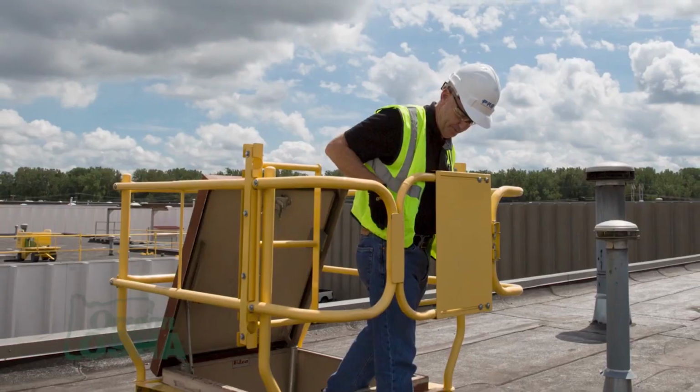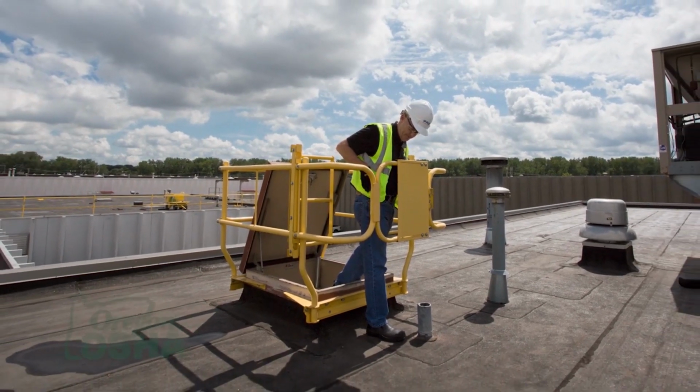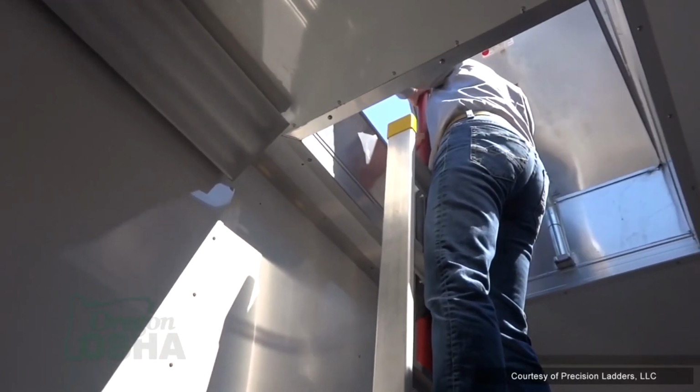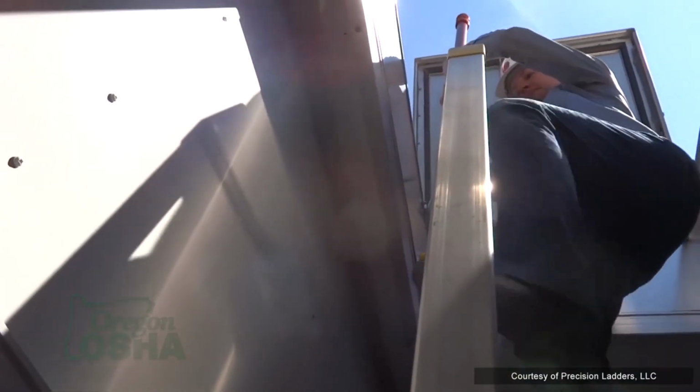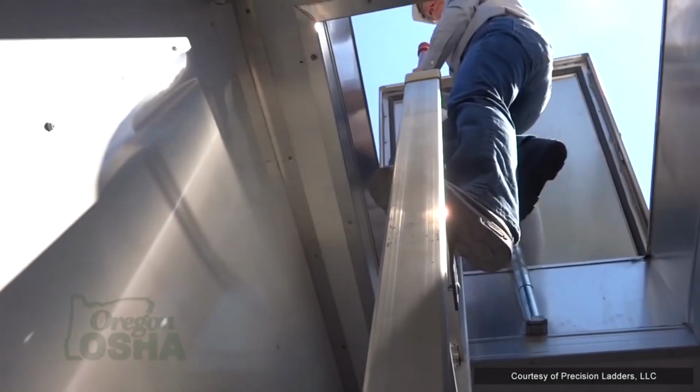If it's an older building where they did not install one of the extendable handles that are now available, or if it's one of those types that doesn't have the perimeter around that hatch. But getting out of the hatches, sometimes you climb up the ladder and then you grab the top of the hatch and then you're stepping up and you don't have anything else to hold on to. So what we try and promote with our customers is to install those extension poles that you can put inside the hatch. You get to the top of the ladder and you can grab the handle and pull it up and it locks in place and it gives you something to hold on to when you climb up out of that hatch.